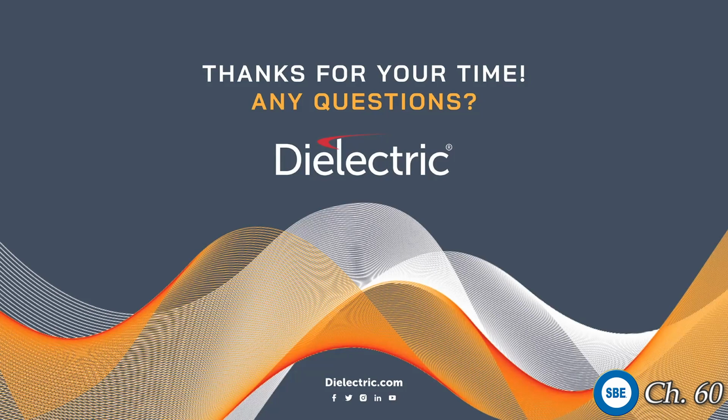Thayer, just a quick question, you may have covered this, but is there much difference in bandwidth between ATSC 1 and 3 that would require a new antenna for many stations? I don't think so. Your low band can be a bit difficult because you have a very low frequency that you're trying to couple to. As long as you have bought an antenna from us since repack, it has that future fill option and it can be converted very easily.